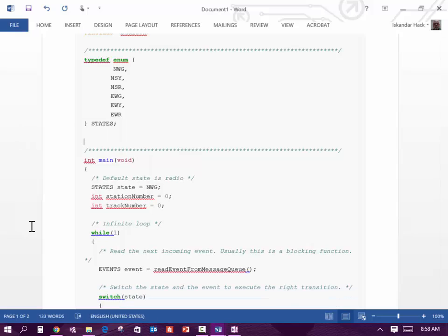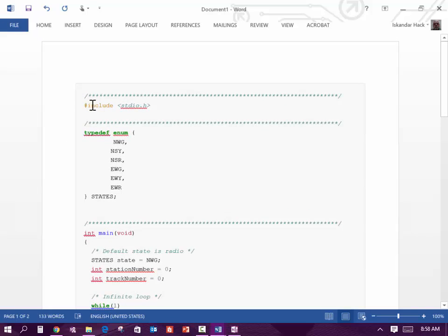Now, when I get done with this, it is not ready to run because you have to incorporate it with the rest. This here needs to be added. This includes standard IO.h. That would include our 8051 F850.h or something like that, I can't remember what the name of the file is, but it would include that file.